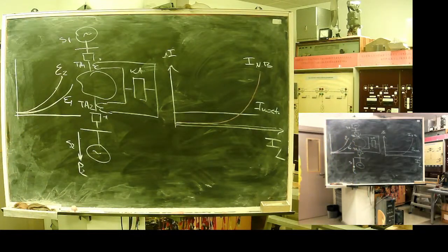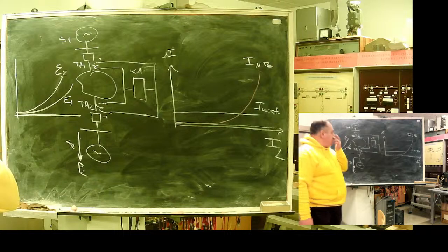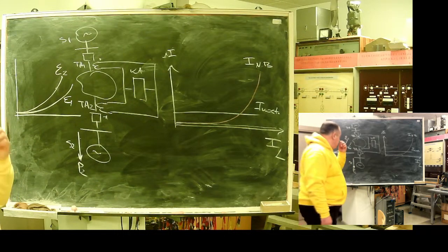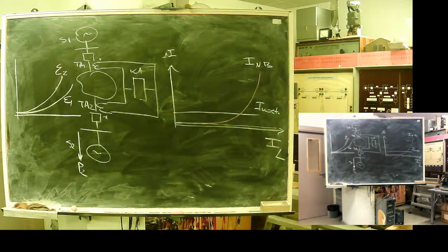We need to solve this problem. If we deal with transformer or generator protection, we need to sense interwinding faults, and they are characterized by a change in current of less than a percent. At an early stage of fault, the difference in case of an interwinding fault will be less than a percent. We need a highly sensitive relay. This flat version will not work. We need something better.